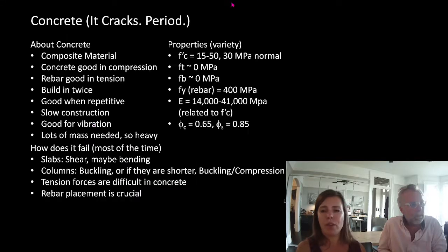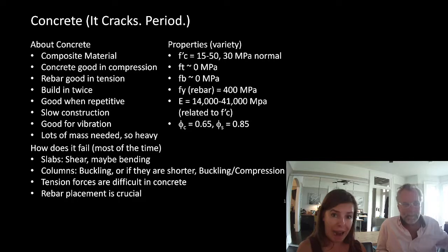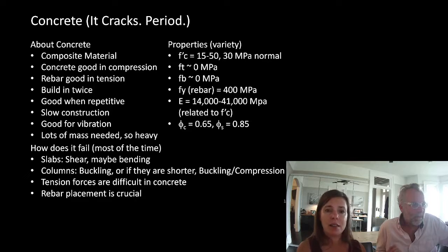Oh, here's the important thing. For you guys, it cracks. Period. Just get your head around the fact that concrete cracks. Always tell every client, every contractor on day one, their finishes, their concrete will crack. I would say probably 50% of lawsuits are about cracked concrete. Structurally fine, nothing wrong with it, but it cracks, and people perceive a crack as a failure. Concrete is meant to crack. We expect it to crack. We do things to help control the cracking, but it cracks. And so as long as everyone understands that, we'll be fine.